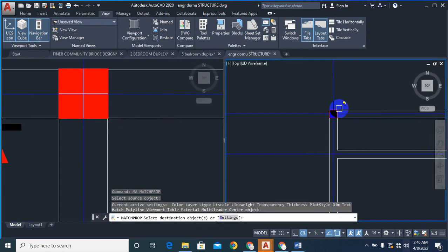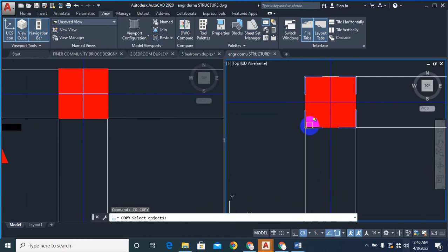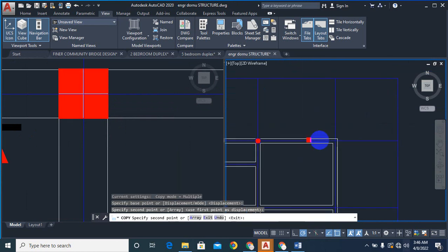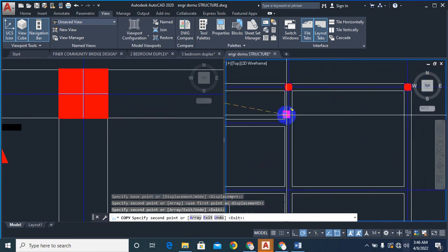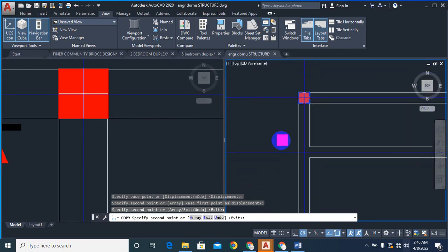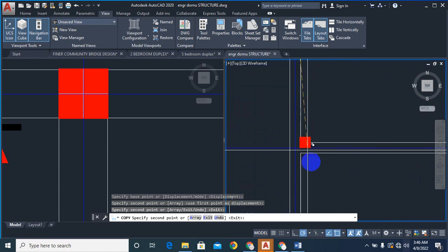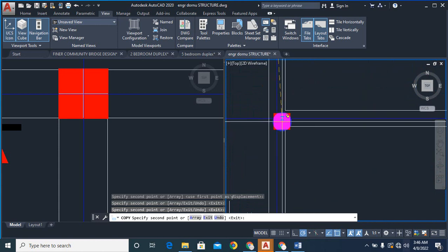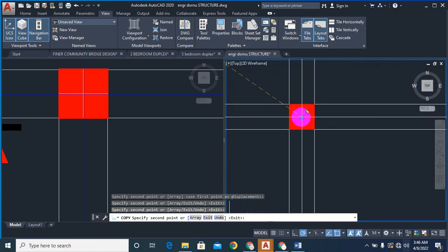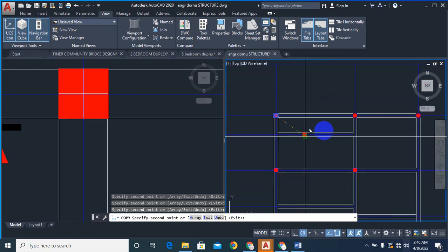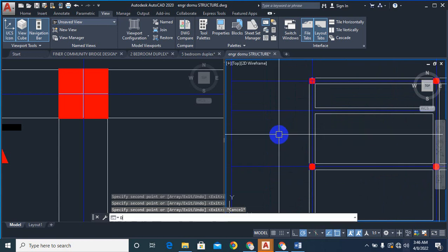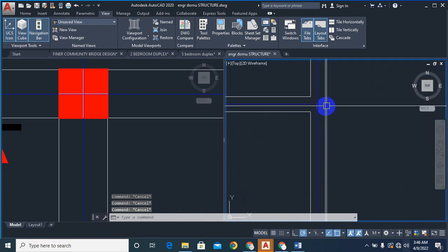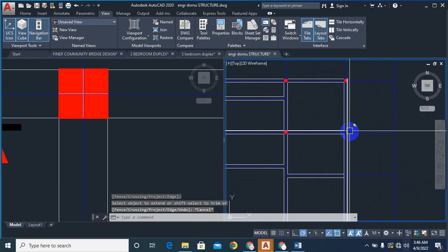If I want to maintain this, since I already have, I can maintain it this way. So you can see polyline. That is actually what Prota Structure recognizes, so it will give you a column. But the moment it's not on polyline, it won't display as a column for you. So you see here now, I can decide to place this here and forget about this without placing a column here. If I place a column here, it's going to make it safer, but as it is right now, it's still safe. Why I said it's safe is if you check the span here, you can see this is even less than 4 meters, so the span is reasonable enough and it's going to carry it conveniently, that I'm sure of.